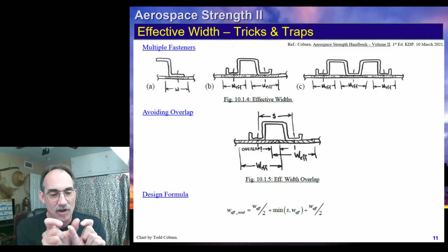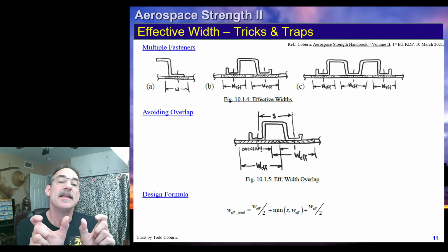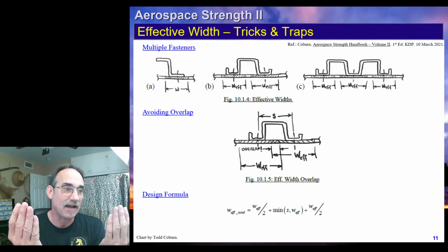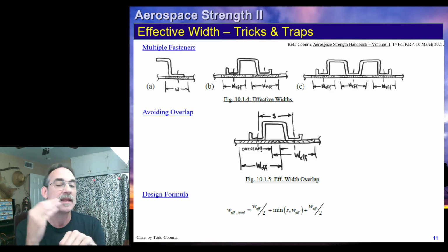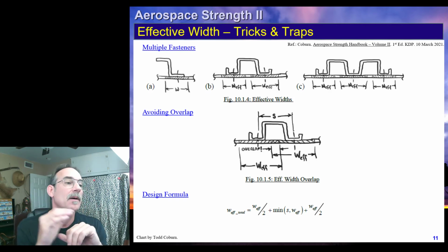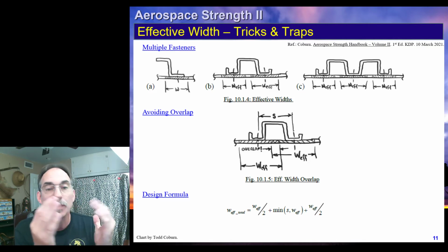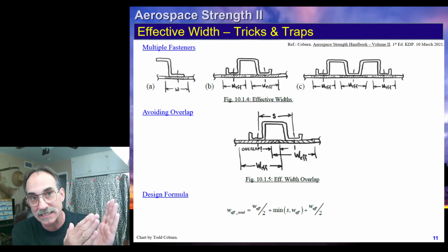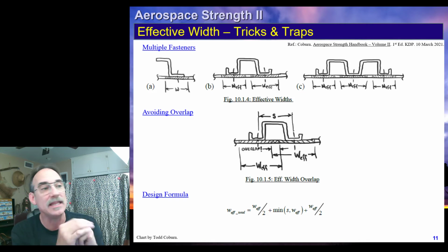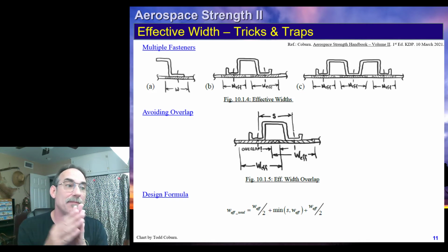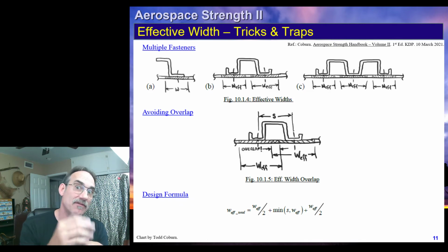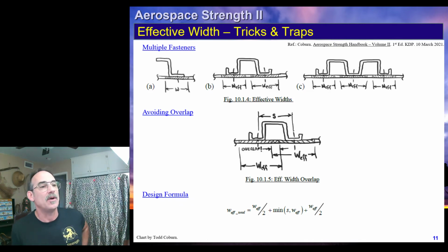If our spacing is large enough, if it's larger than the effective width of skin, then we don't want to use more than is effective, and therefore use the W effective. So W effective over 2 plus W effective over 2 plus the minimum of either the spacing or W effective between those. Now, if any of these occurs on the edge of the panel, you can just adjust it by using that half equation of our edge equation we saw before. Got it?